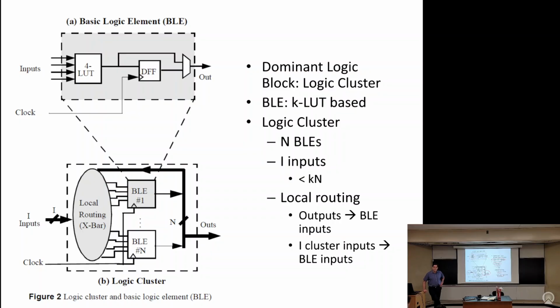Altera did that in one of the chips that we had to write CAD tools for when we were at Right Track CAD, so we didn't architect it. If you use both the LUT and the register, you could only get one of the two. Basically you had 8 LUTs and 8 registers. You could use both, but you could only get 8 signals out. And that was a real pain, right? Because now you had lots of illegal configurations. So while you can do that, I'd say that's not a great idea if that limit is too tight.